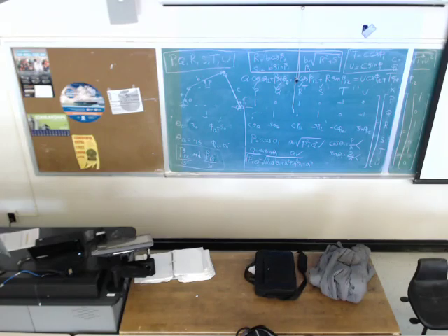So in offset slider crank, for example, for this one, when the crank is moving by 30 degrees from the first precision point to the second, S2 minus S1 should be 1. So the location of the slider at the second precision point minus the location of the slider at the first precision point should be 1.